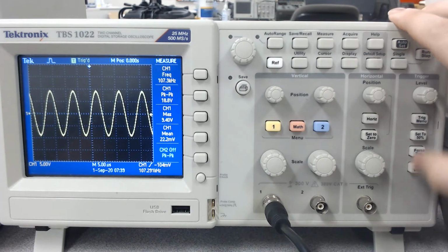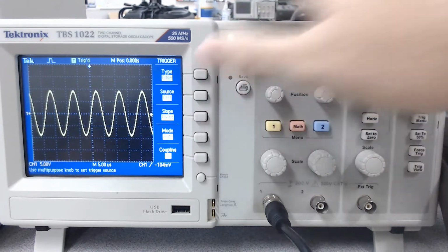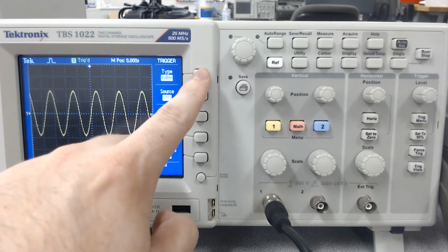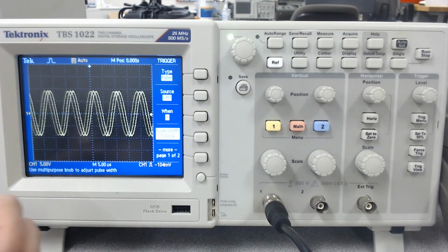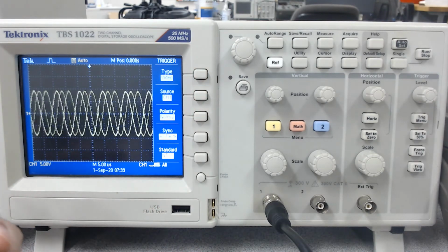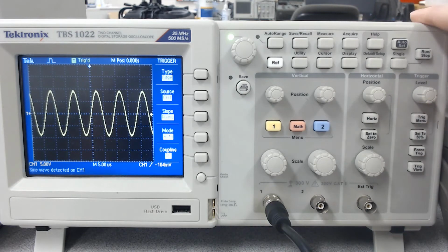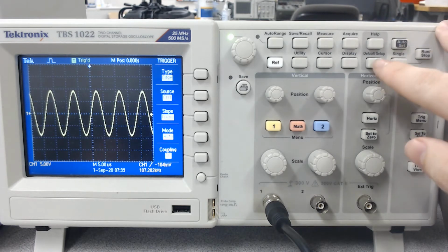We also have some trigger menus here. If you hit this trigger menu, basically this type edge means that it's at the edge here. If we change that to video or pulse, it actually is more of a moving signal. So we really want it at the edge. If for some reason it was moving and you couldn't figure out why, the default, if you just hit the auto set button again, kind of accomplishes the same thing. It automatically defaults the trigger menu to a type of edge. So that's very useful.